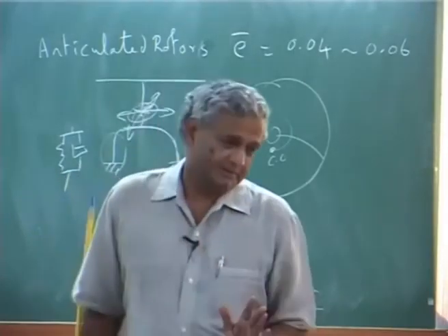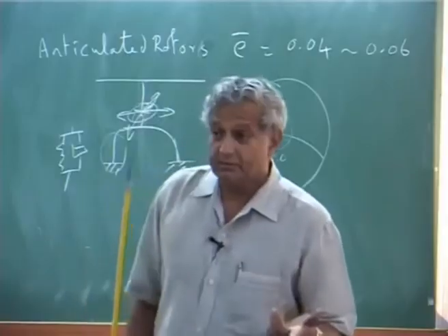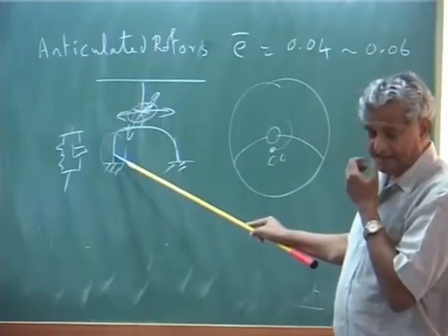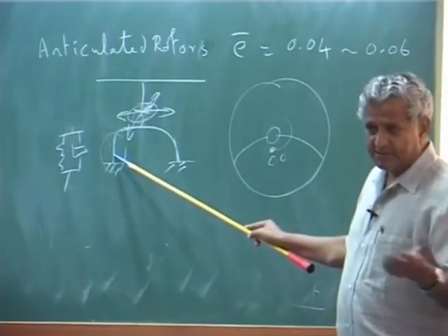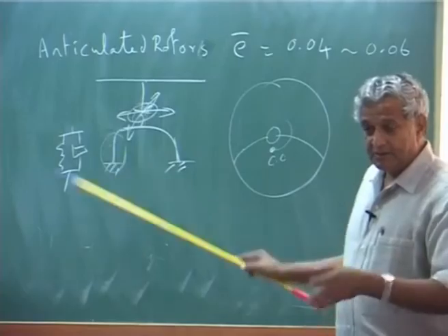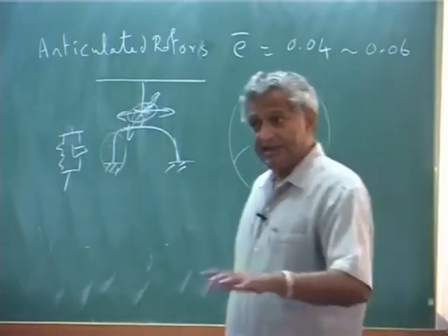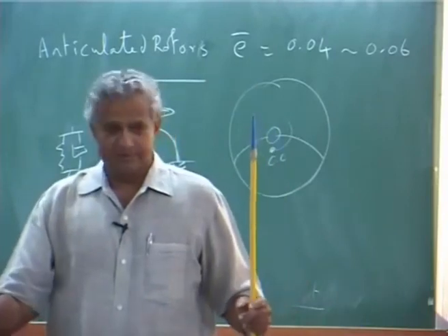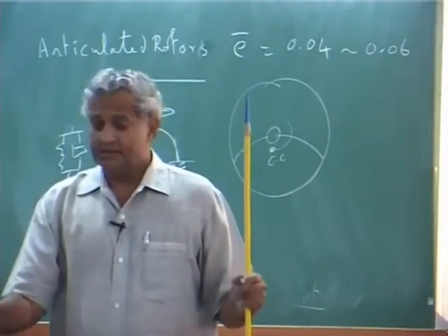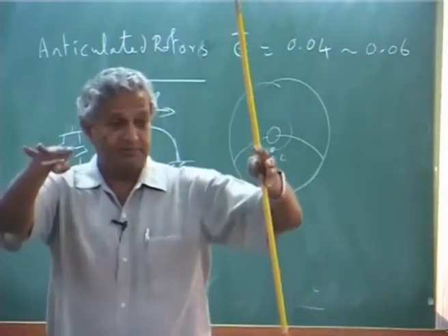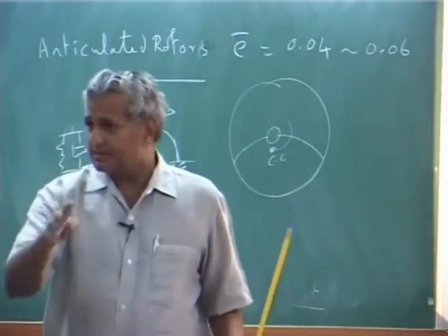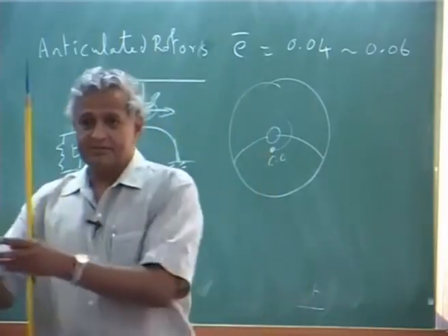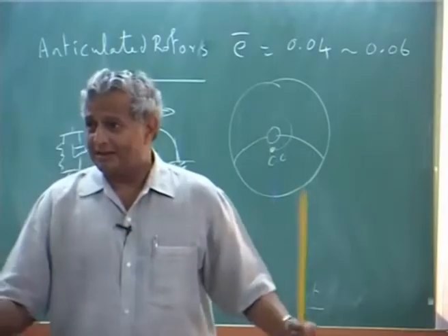you may cross the resonance point, or if you want you shift it up. Best is you put a damper. Now there are two types of thing. One, you can put a damper right on the fuselage, that is in the landing gear, because some of the helicopters have skid landing gear. That is why you have to be very careful whether the skid has its own characteristic. If you go to wheel type, with some shock absorber and other things, that will have a different characteristic. Helicopter may be same. Actually ALH, yes, they had one version which is the skid, another version which has this wheel type.